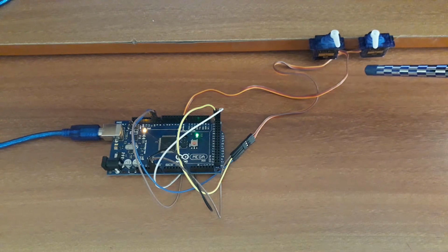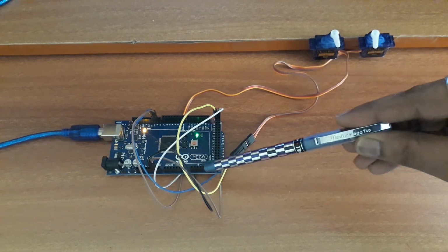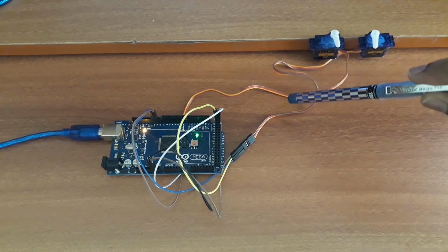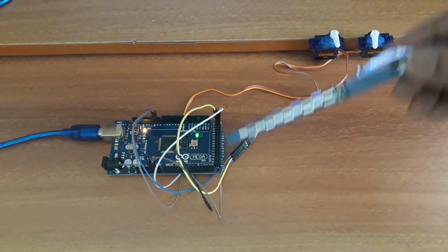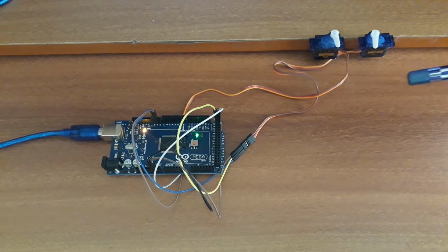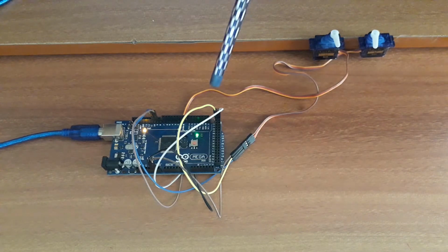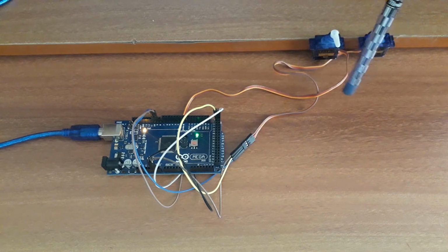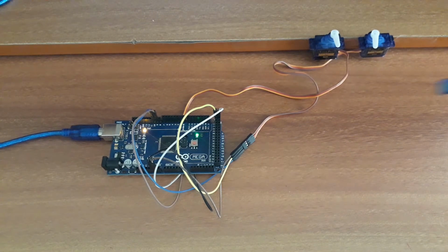Now here, this is the left motor and this one is the right motor. For the left motor, with the help of that blue pin, I connected digital pin number 10. And for this right motor, the signal pin, we can see somewhere here below this Arduino board, is connected with pin number 9, and the remaining two pins are the power supply and ground. Already I connected them. It is easily visible as I'm using the Mega. Then here the 5V supply is already available. One pin I gave to the right motor, and the white pin I'm giving to the left motor. This is all about the circuit for this Arduino motor.